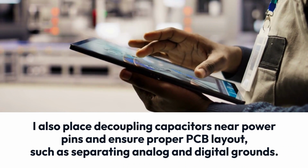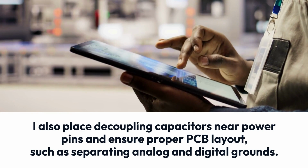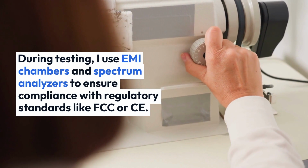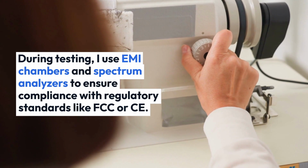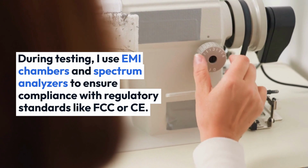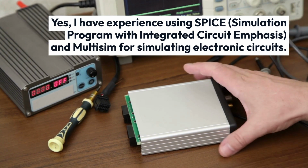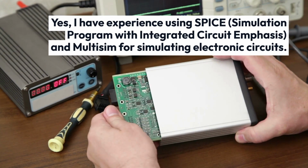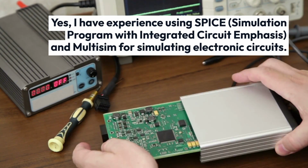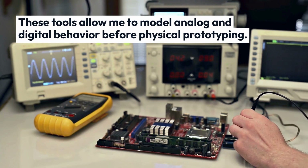I also place decoupling capacitors near power pins and ensure proper PCB layout, such as separating analog and digital grounds. During testing, I use EMI chambers and spectrum analyzers to ensure compliance with regulatory standards like FCC or CE. 13. Have you worked with any simulation software like SPICE or Multisim? Explain. Yes, I have experience using SPICE, simulation program with integrated circuit emphasis, and Multisim for simulating electronic circuits.